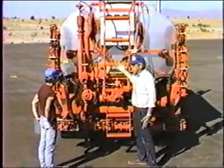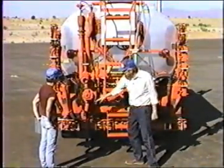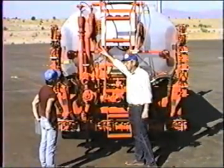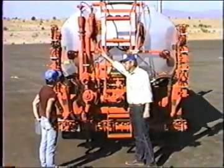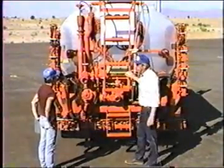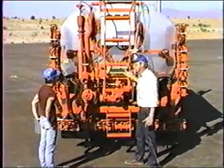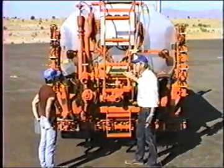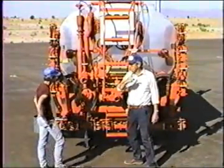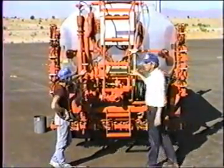Okay, if we forget the master switch and leave it on, that equalizer valve is opened, as well as that equalizer valve and that equalizer valve, and the relief valve is closed, also discouraging circulation. Nothing is circulating. It is just sitting there cooling off in this nice cool breeze. And if that goes on for 30 or 40 minutes, when we go to use the truck again, when we go to spray, everything's plugged up. And again, here's all these dump trucks sitting out here, and rollers and chip spreaders, and we're running around here trying to figure out how to get this thing thawed out. It's a real embarrassing place to be.